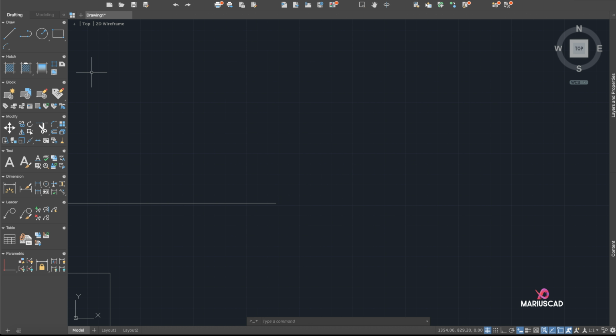Now I can also use a line, okay, from the exact point, press the Alt key. I will type now the length, which is 100, and again this symbol, and I will type 30. So I have again a line of 100 units at the angle of 30. Another option could be to activate this polar tracking, and here press right click and select 30.